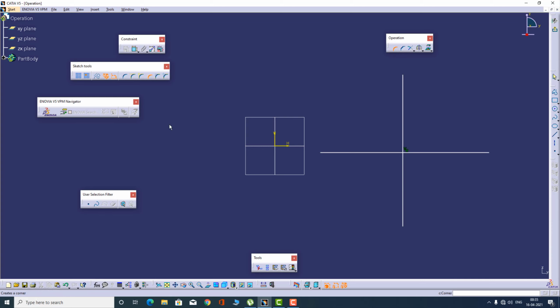Okay, the other option is basically construction line trim. If I select this option, select the lines. Okay, so here you will see that from the point to the arc, to this corner where the corner meets the line, that line has been turned construction, but beyond that point the lines have been trimmed. Okay, so this is known as construction line trim.